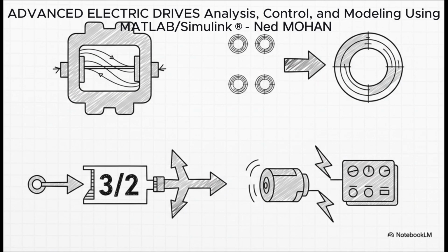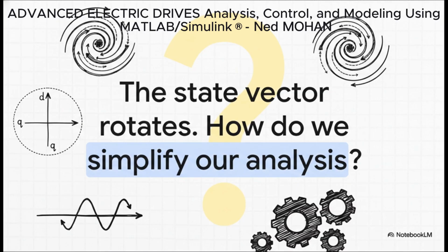All right, let's just do a quick recap. First, space vectors come from the real physical magnetic field in the machine. Second, they let us pretend a three-phase system is just a single winding, which makes life so much easier. Third, they connect back to phasors through their direction and that critical 3/2 scaling factor. And finally, the whole point is to give us the tools to handle the dynamic, messy, real-world behavior of electric drives. So, that leaves us with one last big idea to chew on.